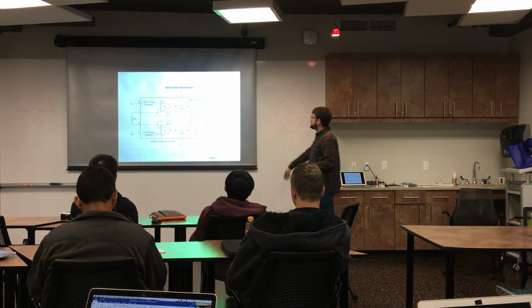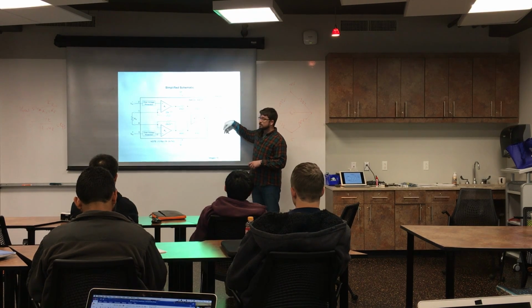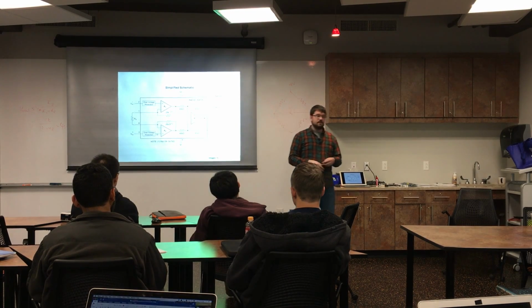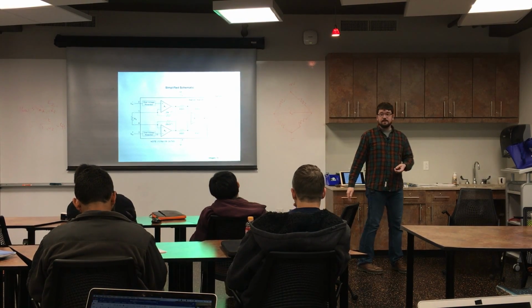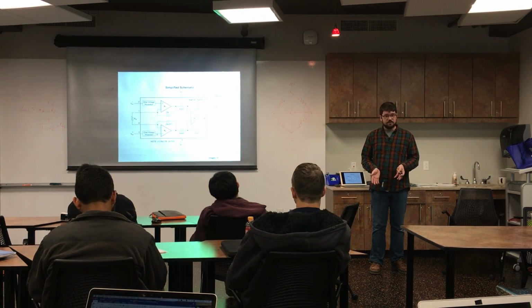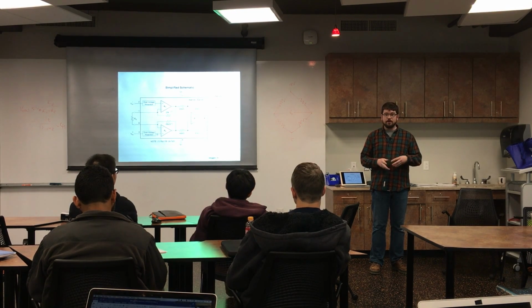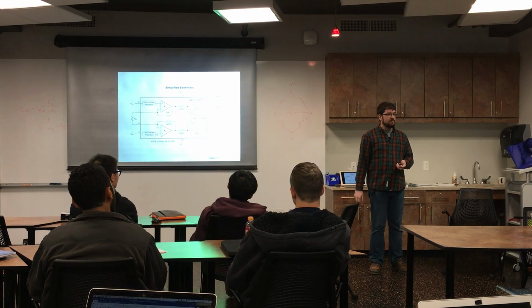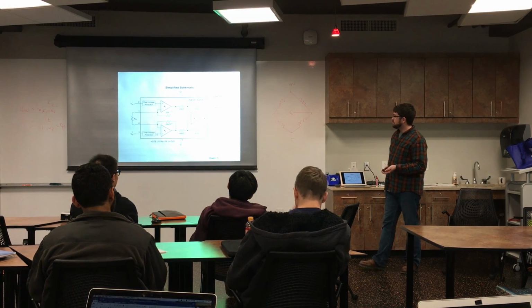And then they provide formulas for you to plug in so you don't have to do all the circuit analysis yourself. You can set what gain you'd like. They also have tables in the datasheet that say if you want a gain of 500, you can use this standard 1% resistor that you can buy and it'll get you a gain of 498 or something close. The closer you want to get to your absolute gain value, the more expensive the resistors get.